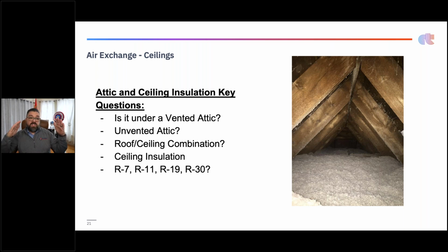If this is a roof ceiling combination, right? So if you have like the second floor of a Cape style home or a colonial and there's a vaulted ceiling, if the ceiling roof ceiling combination, you can only fit so much insulation in that 2x4 or 2x6 or 2x8 or even 2x10, hopefully construction. And the ceiling heat loss actually gets greater compared to just blowing in a stack of cellulose there, right? So there's some options on those forms and there's some options in the software. Just make sure you're actually seeing what the insulation value is.